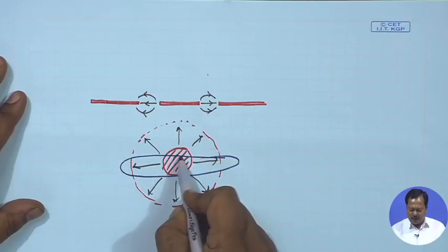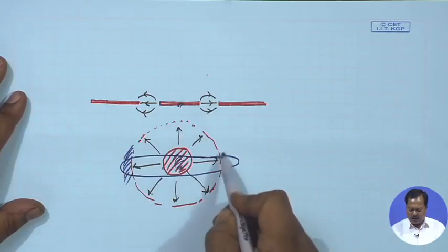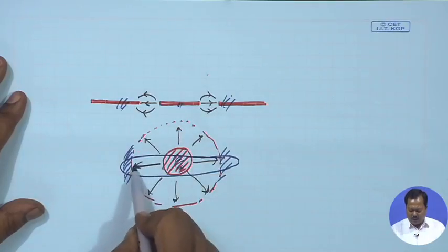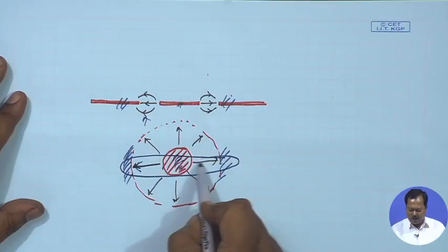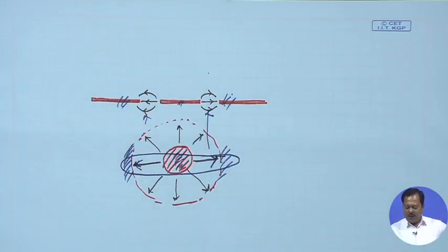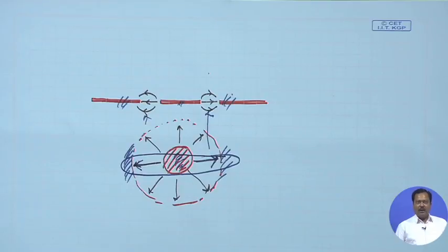We will be soldering the central conductor to the signal line and this outer conductor, this part, to the ground plane, and then this component of the electric field will excite this component, and this right-hand side component will excite this component. So, we do not have any problem due to field matching, and in both of these two different guiding systems we have quasi-TEM mode. If the characteristic impedance of both the CPW line and the coaxial cable is 50 ohm, in that case we can directly connect it without using any impedance transformer.